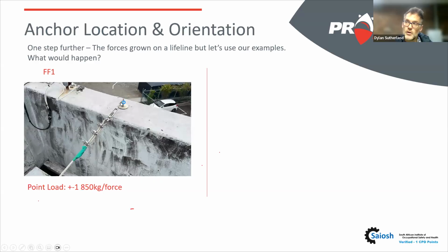But would this eye withstand a pulling force of 1,800 kilograms? Would this hook that is not even closed withstand a force of 1,800 kilograms? Would this turnbuckle withstand it? Would these clamps hold the cable in place and not let the cable pull out? Now, these are the things that we need to be considering if we're working in fall factor 1 and making sure that we understand that is the risk.